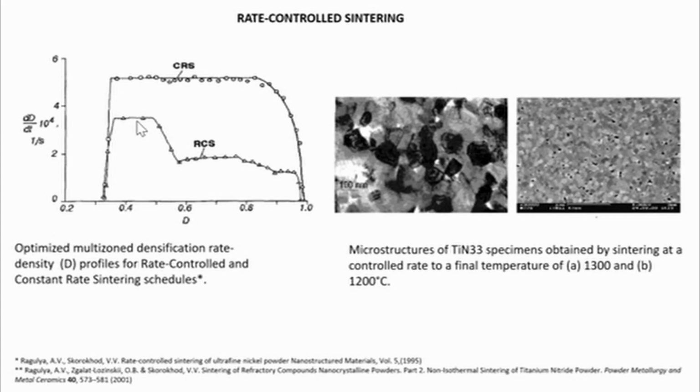However, the controlled sintering of carbonyl iron powder displayed that it's possible to apply it not only for ceramic materials but for metallic materials too. The rate control sintering technique was used as a structural-oriented type of sintering that substantially limits the grain growth compared to conventional pressureless sintering, and produced dense ceramic with high hardness, fracture toughness, and stress. It was reported